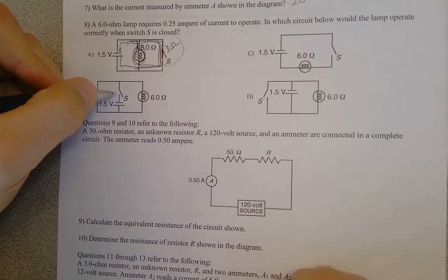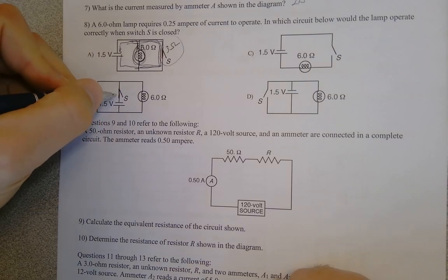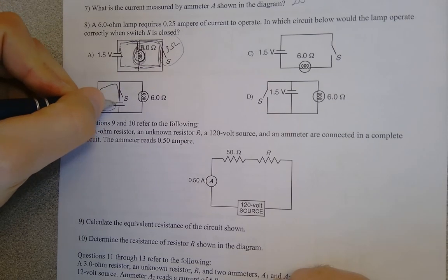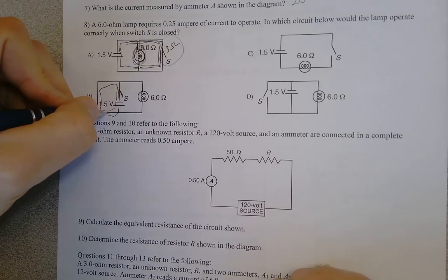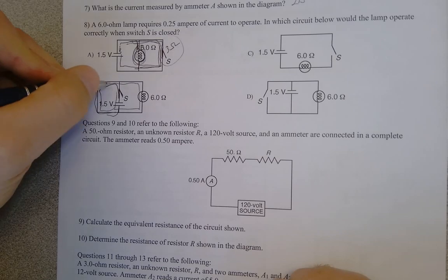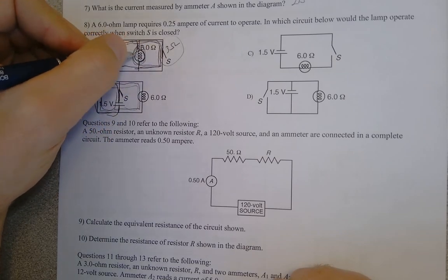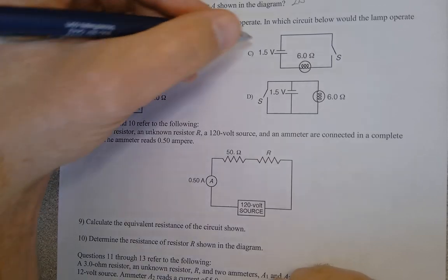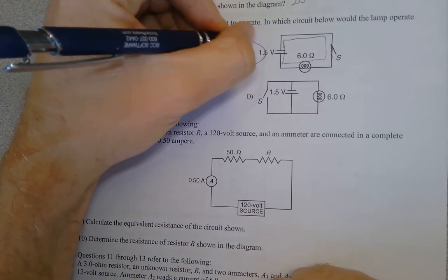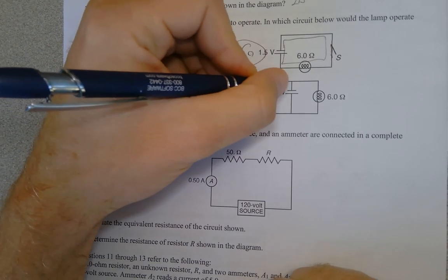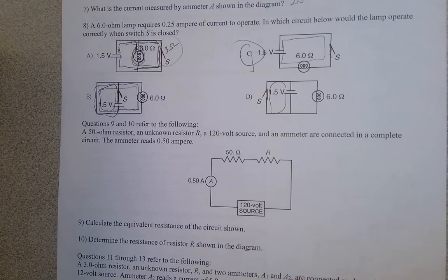All right, so I look at this one. If I close this circuit, I have a short right here, so that would not work. When the switch is open, you could have electrons go this route, so before I closed the switch, you made a short. Same thing with this one. Electrons could go here first. When we close this one, now it's got one loop. So the C looks good. When I do this one, again, I've made a short in parallel, so that one's no good. So C is the one that makes sense.